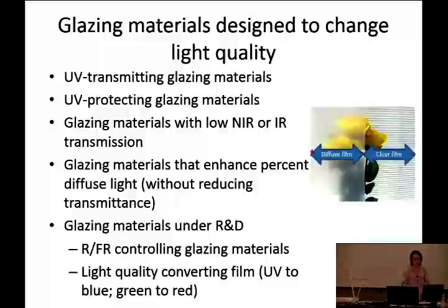Yes, Hailey. Well, I know that Kenneth and I took Dr. G's greenhouse engineering class last year, and I think that the structure, like the shape, really depends on where you are. Because I remember Dr. G telling us that the sawtooth was originally designed so those vents on the vertical sides could open for ventilation, but it's so dry here that we don't do it because then we lose all the moisture out. So it really depends. Yeah, Hailey is saying that design should be selected based on where you are, what climate you have. Exactly, yeah, you are correct.